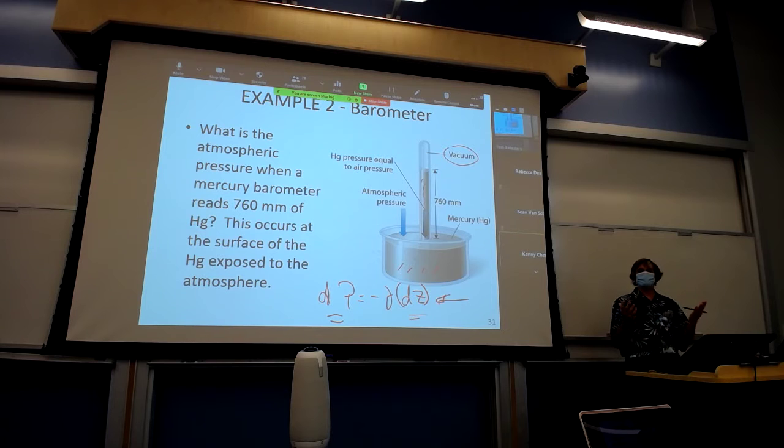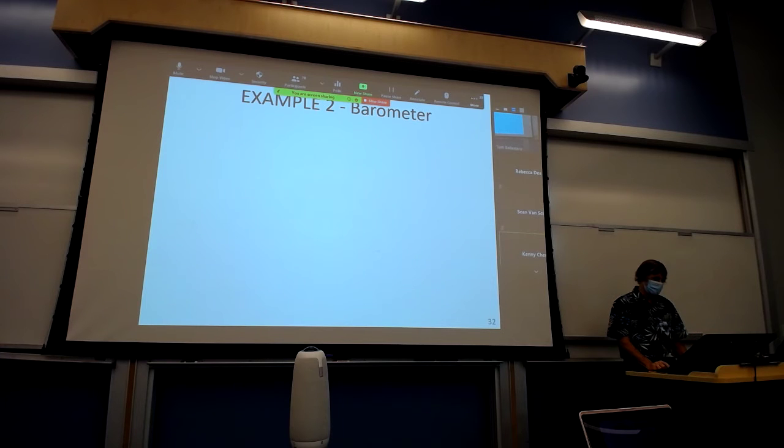And again, it seems so obvious that there's a continuum. When you leave here in practice, it's not always that obvious. Why? Because all the pipes are underground, and you don't know if some of the pipes are filled with air or not, because you have cavitation or some way of air getting into the system, backflow. So again, it seems obvious in a lot of the cases we look here. When you leave here, that's the challenge. You never really know unless you can see the complete system.